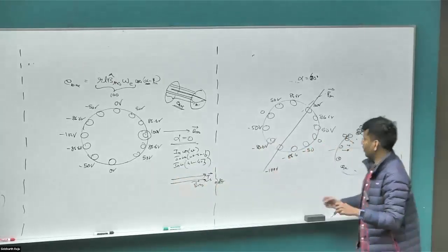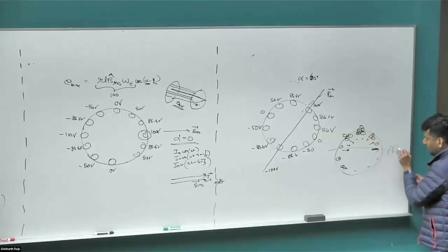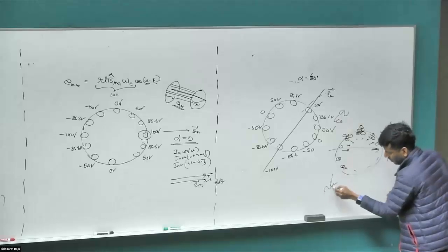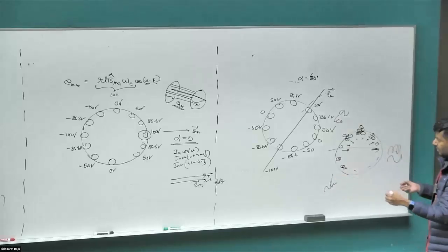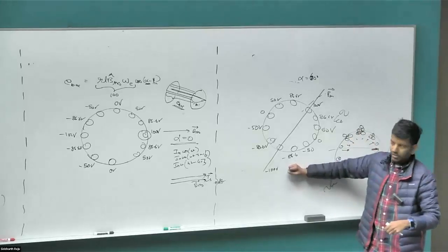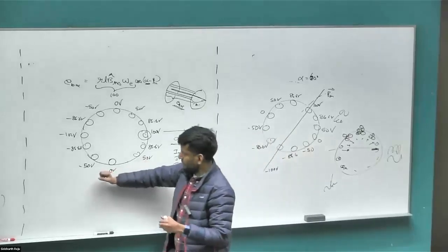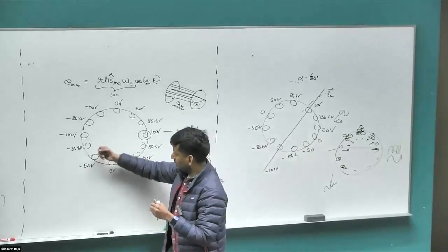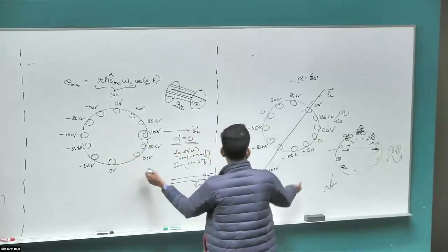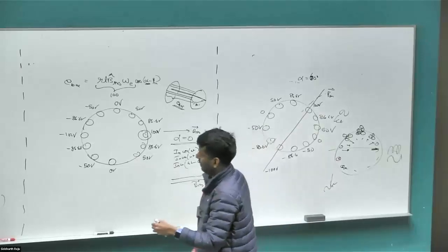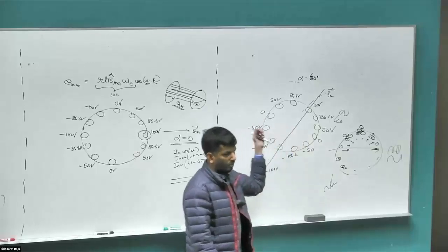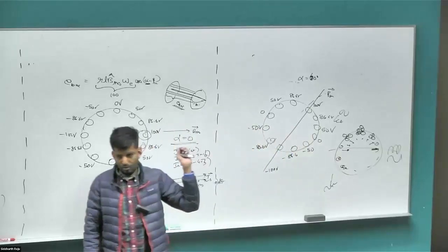The second process, as time goes on, what we did is in the A phase, we started pumping currents that are moving sinusoidally. In the B phase, current sinusoidally, C phase, current sinusoidally, and each of them shifted by 2 pi by 3 from one another, so that this whole distribution will now rotate. And that is also being achieved here. Right? The physics of it says that it would create a magnetic field that would rotate, creating effectively the same as what the stator was trying to do with so much complication. The rotor is just simply doing it without putting any effort into it. Just a bunch of rotor shorted bars.